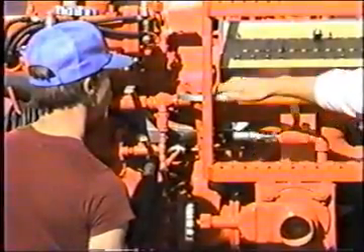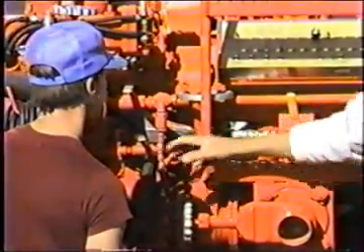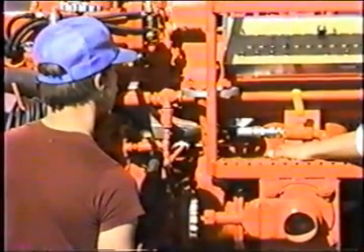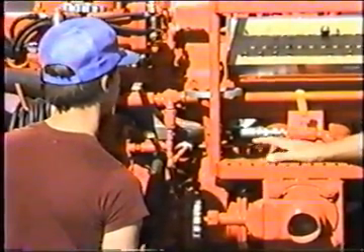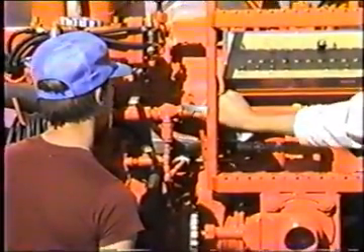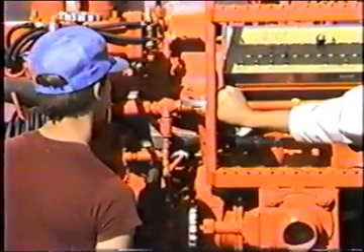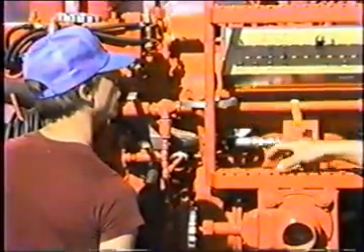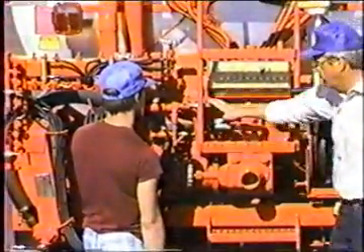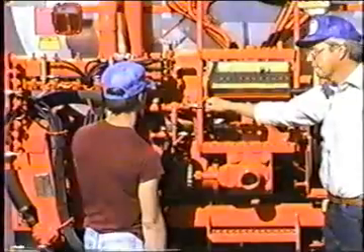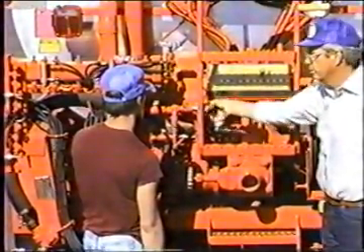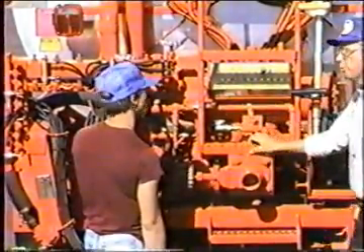In that situation, we'd want to close this valve and isolate the pump from the product, just so we don't have to clean out the pump after we've done the unloading process. Since that's seldom done, 99% of the time this valve is going to be open. So I say just leave this valve open all the time and only close it in the situation that you are going to gravity off or pump out of here with a different pump. Just close it then and then open it back up when you're done. It's a multi-turn valve, and when it's got asphalt in it, it's kind of hard to turn. So since most of the time you're going to use it open, just leave it open.